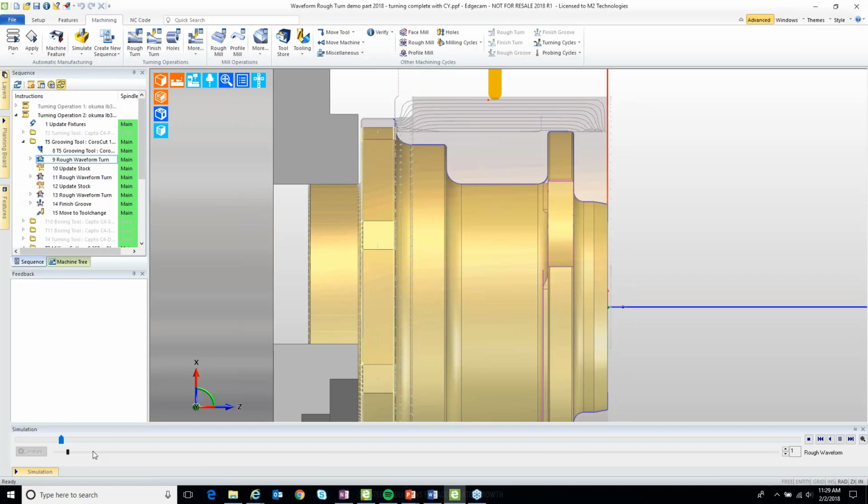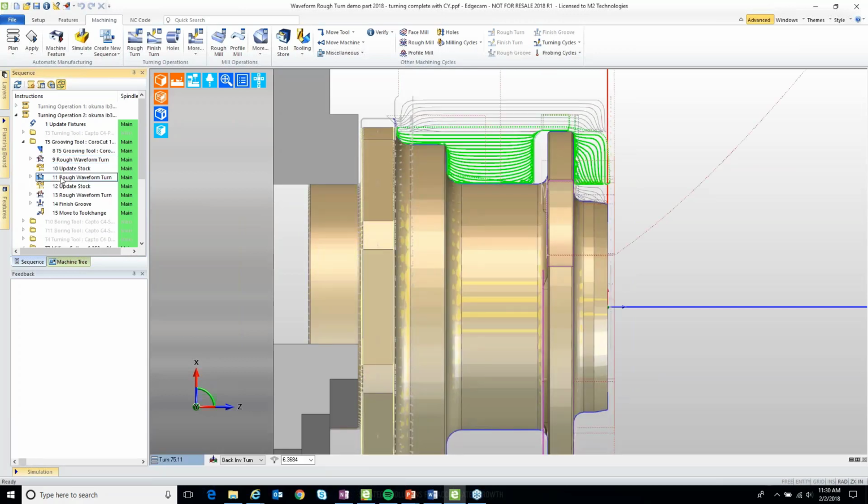We see the chip thinning effect of a full radius insert. Very good for machining with ceramics and some materials, as well as many groove tool applications. The tool will take the material down until it's reached that step height. I'll stop simulation there. And then we've intentionally split out another cut to now come in. There are a variety of reasons for that, ranging from insert changes in some super difficult applications to just chip control or process control as well. And then a third cut to go attack the small bottom area.